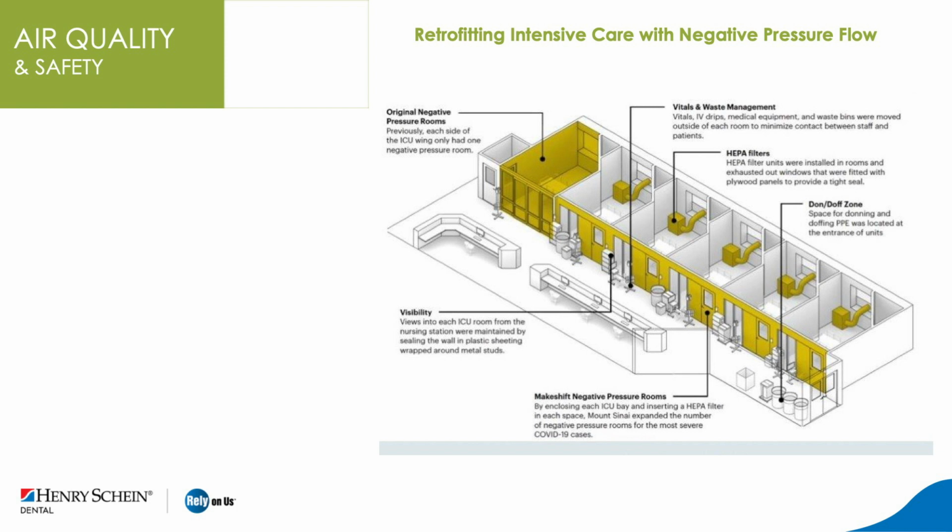But I'm going to say that almost always retrofits are unique workarounds because the infrastructure of an office varies. I mean, in this example, the hospital was fortunate to have the intensive care unit on an exterior wall for venting, because they had to vent every one of those mobile negative pressure units to the exterior.